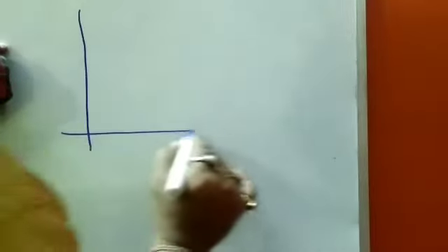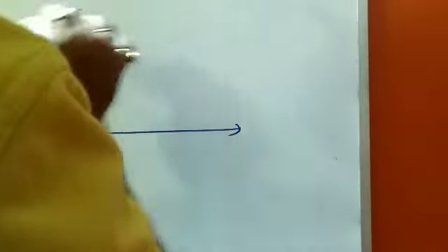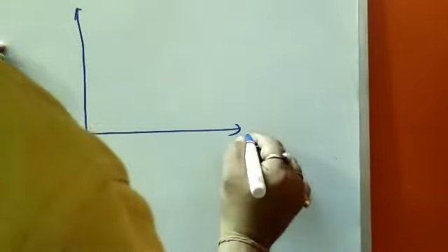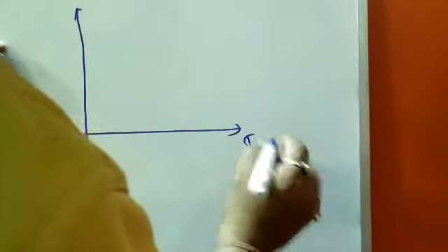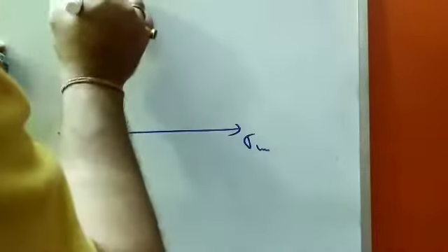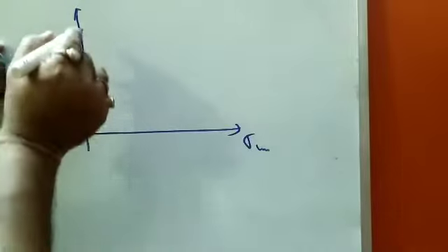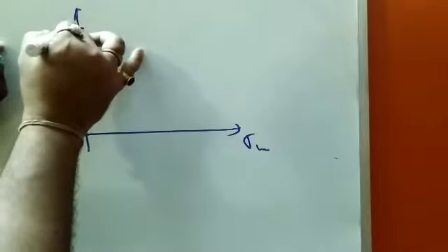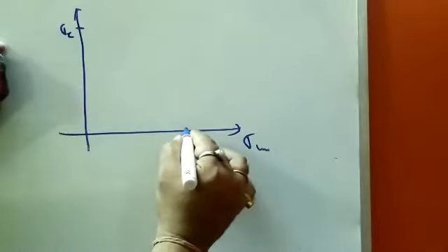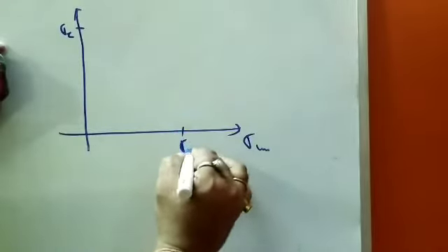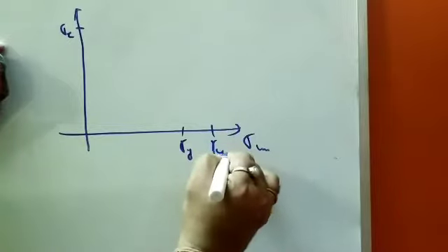Now we have rubbed this and we'll draw a fresh line from here. This axis represents the mean stress, and this one represents the amplitude stress. Now all failure points are there. I'm not drawing the failure points because it makes it clumsy. And over here I consider the endurance strength, over here the yield strength, and over here the ultimate strength.